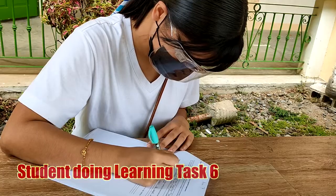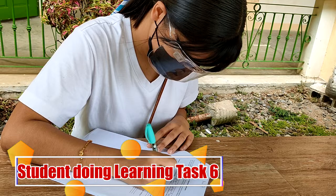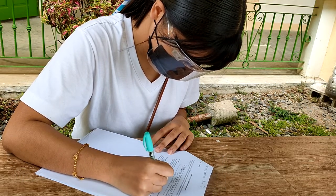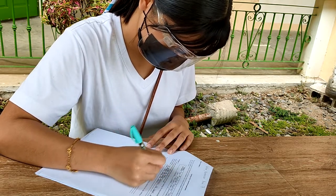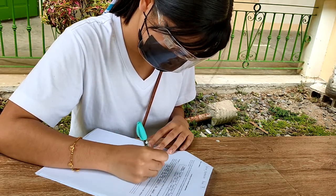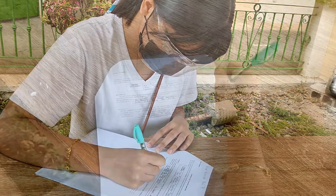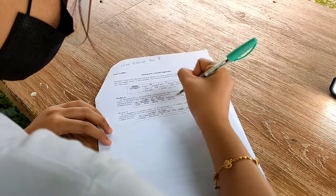Hi, I'm Veronica, grade 10 student of Buenaventura Alandi National High School. For the first situation, the welding essential is length of arc. Mr. Nico should maintain the correct length of arc while doing the welding process. For the second situation, the welding essential is current setting. Mr. Evangelista should set the correct current setting to avoid having the weld bead wide and flat with excessive spatter